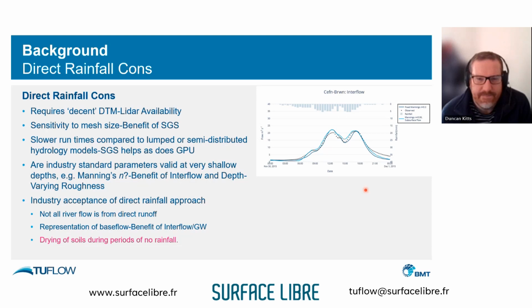Right. And second question before leaving, Quentin asking his own on rain on mesh methods. Do you need to prepare some kind of hydrologic ready DTM, like filling the lowlands and so on? Because we've seen that this can have a big impact on the first losses, with the first part of the rainfall just filling all the ponds and so on.